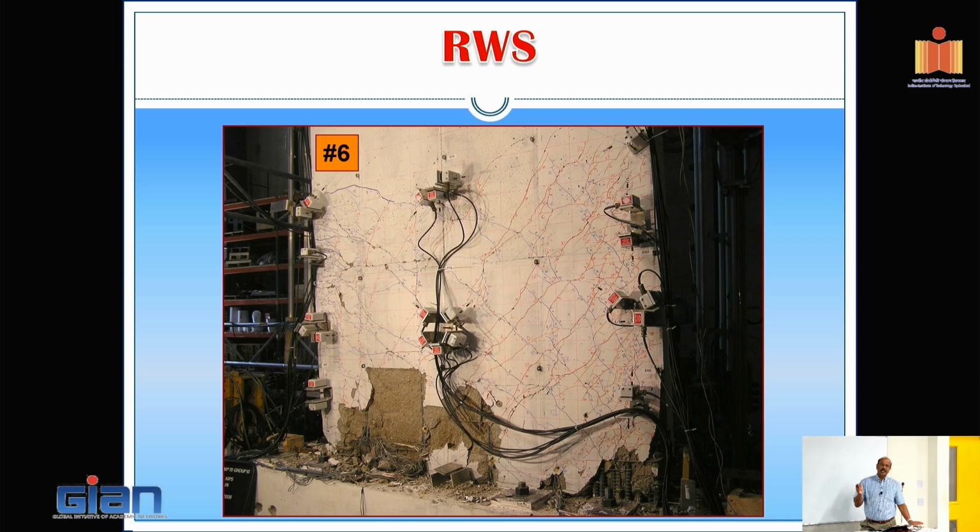So in the lap splice case, basically the splice becomes weaker and the wall was failing sooner, and you can see the damage was concentrating due to the dilation, which typically happens as the plastic hinge forms and causes damage to the wall panel. So this wasn't the case in the previous two cases. When the coupler was put in, the behavior is different. So I think especially the students learning, try to focus on behavior. That will tell you how well the system will perform and not perform.